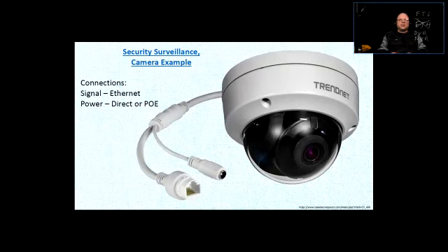Sometimes there would be cables sold on the market that would be called Siamese cables, just like Siamese twins. So there would be a Siamese cable that, in one jacketing, would be coaxial cable, and it would also contain a one pair stranded for power. Right? So you don't have to run two cables into the camera. So those would be there.